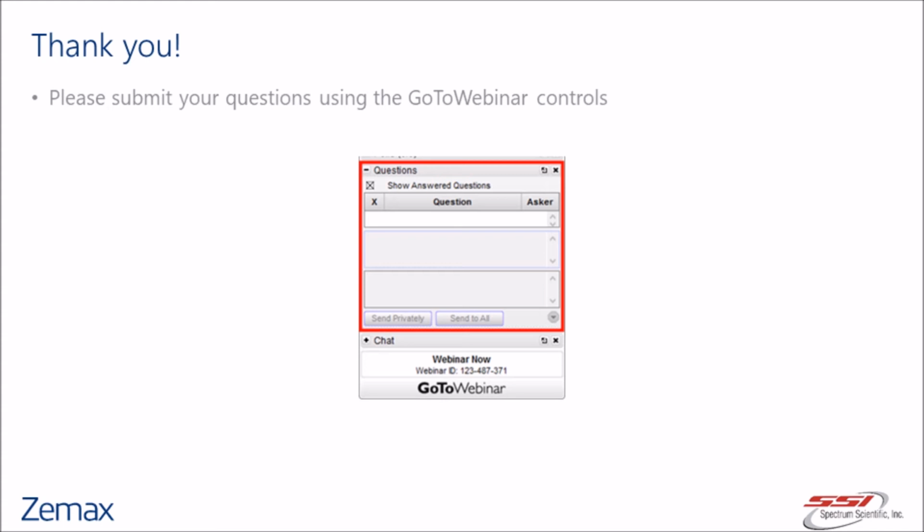Now that said, if you've found a pretty nice solution, hammer can be a useful thing to do. If you turn on hammer and let it run overnight or something, you'll really ensure that you're at the bottom of that local minimum and that you've really found the best solution in that area.